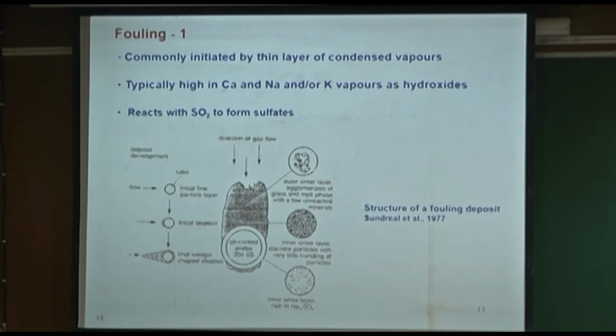Then you have inorganic sulfur, which means it is bonded to the other coal minerals, calcium or iron or sodium, etc., difficult to dissociate. So that actually forms sodium sulfate or calcium sulfate or iron sulfate or a mix of those sulfates. So that's the inorganic sulfate. Then you also may have, not always, pyritic sulfur, FeS2. And if that happens, then you've got a problem.